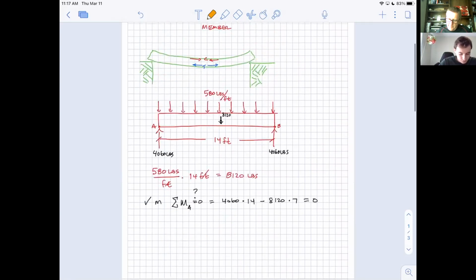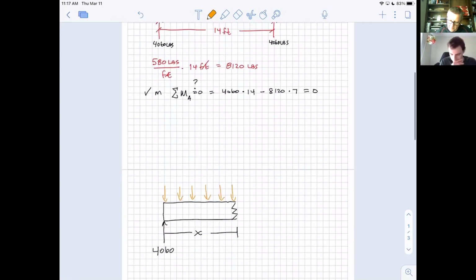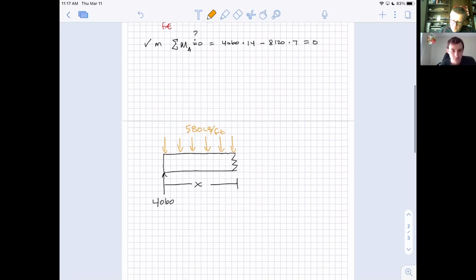And we said that was 580 pounds per foot up there, 580 per foot. Do you see, this is very important, do you see that the sum of the forces in Y now is not equal to 0? So the interesting thing about equilibrium is I need the entire beam not to move, but I also need all the pieces not to move.